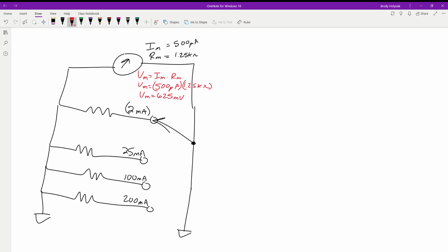Okay, so when this is operating, the other thing we have to look at is, in this circuit, where's our power supply? There is not a power supply, because this thing is going to be another passive meter. It doesn't require any voltage on its own to operate. The voltage and the current it's going to get is coming from what we're measuring.